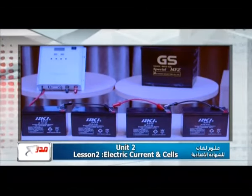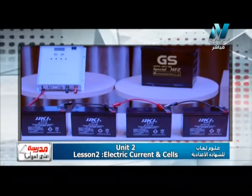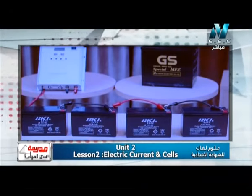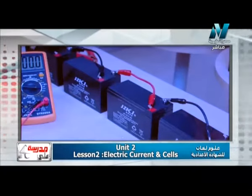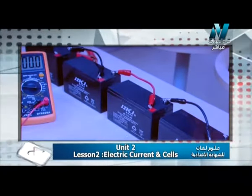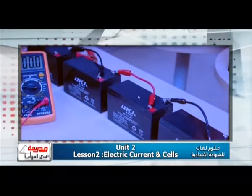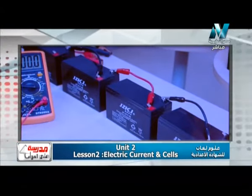And why do we connect them like that? To obtain maximum electromotive force. Each positive pole is connected with the next negative pole, or each negative pole is connected with the next positive pole. Okay? We can see now they are connected in series connection.